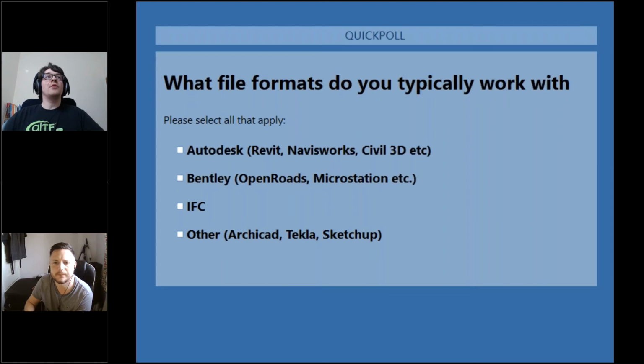So we don't optimize the geometry itself, and the reason being is that your architecture and design staff need to have full transparency. If we were to deform the geometry or reduce the level of detail in some way, for many people it would be totally fine and perhaps even helpful, but for some people it could result in information discrepancies between users of different applications. So all the mesh batching is doing is optimizing the CPU side to reduce memory and to reduce the number of draw calls. We can load a number of very large models.